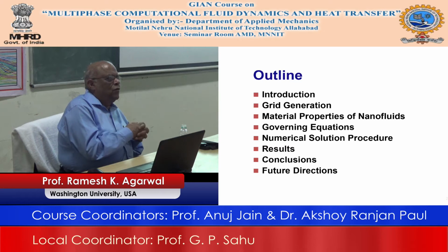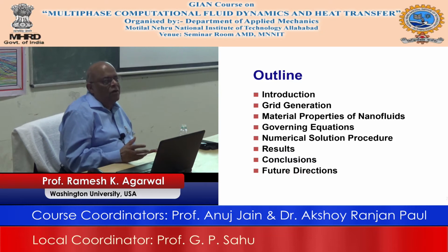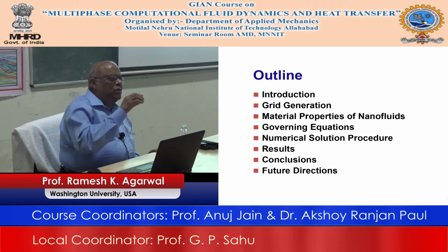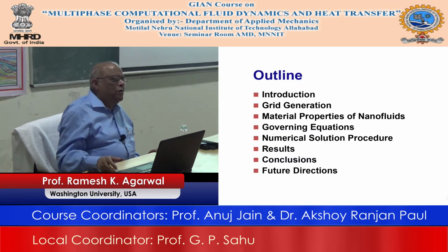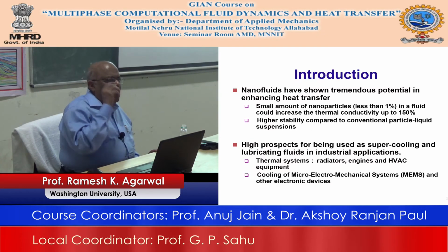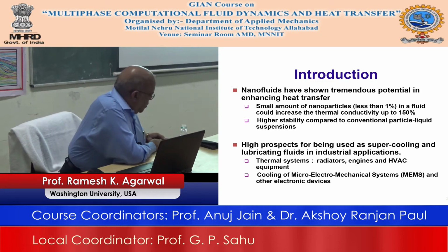And as you said that for 8% you are not getting good results, it could be a factor of many other things other than the model itself. I just gave you an answer, but I think it could be a lot of other CFD related issues that you have. Okay. So for the cavity flow, one of the critical issues is that there are singularities at the corner. I have already talked about this, and there is no need to belabor it again.